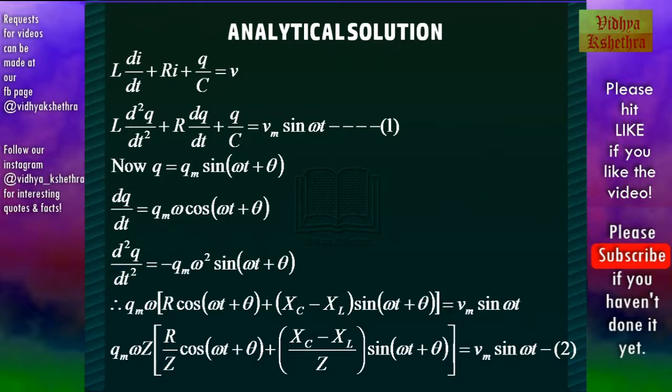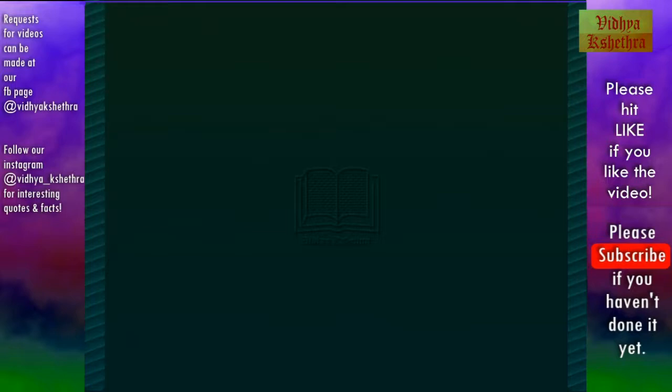Now if we multiply and divide by Z, it becomes qm omega Z into [R by Z cos(omega t plus theta) plus (XC minus XL) by Z sin(omega t plus theta)] is equal to Vm sin omega t. Let it be equation 2.